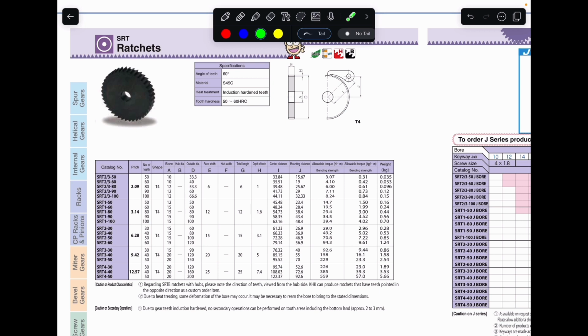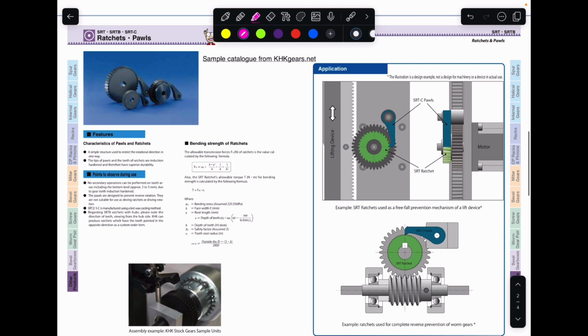So for example, we have one here with 8.24 Newton meter. If that is the expected load, right? So if we were to exceed that, or we exceed that with the safety factor, for example, we go to 20 Newton meter, then it means that the ratchet and pawl system could fail. Right, so this is why you would see that your lift would have a certain load rating. It doesn't necessarily mean that of lifting the motor, but it will also be that of the limiting factor of the ratchet and pawl system.